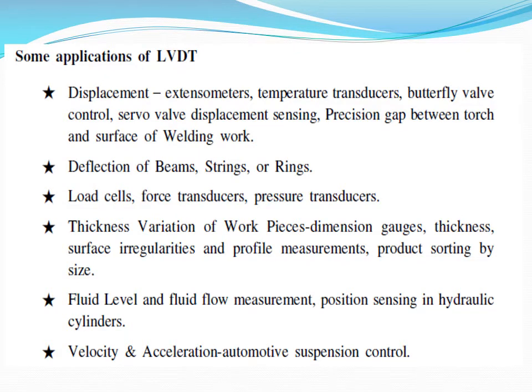Some of the applications of LVDT: displacement monitoring, that is extensometers, temperature transducers, butterfly valve control, servo valve displacement sensing, and again the precision gap between the torch and the surface in a welding area can be monitored through LVDT.